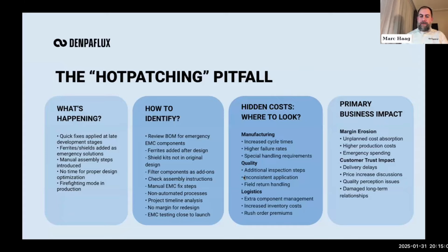Well, you could do a BOM review, for example, where you look into it and see what the materials are and what purpose they have. Are they for performance? Are they for the security of the product? Or are they for EMC-EMI? Once you have identified those, you can look into it: can I delete them? Can I redo some engineering work here, design changes, so that I can take this out of my BOM?